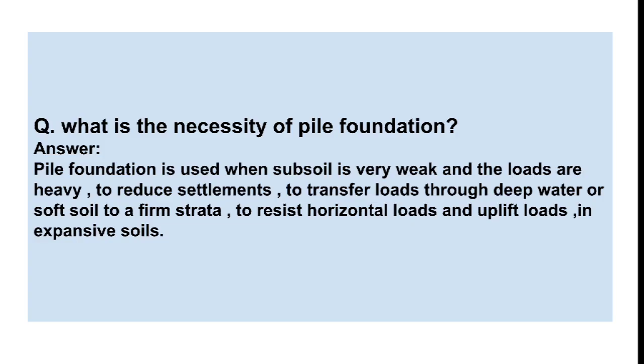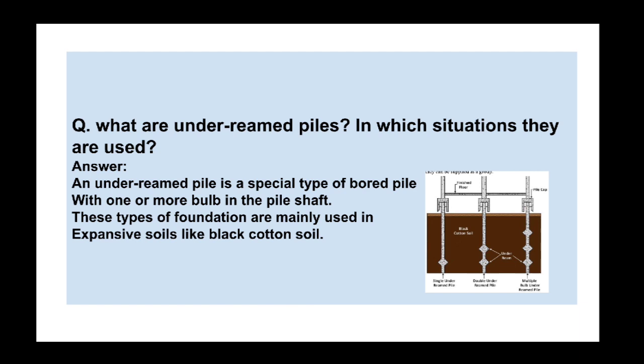First question. What is the necessity of pile foundation? Generally, pile foundation is used when subsoil is very weak and loads are very high, to reduce settlements and to transfer the loads to deeper layers of soil. Apart from that, pile foundation is also used to resist horizontal loads and to resist uplift loads.